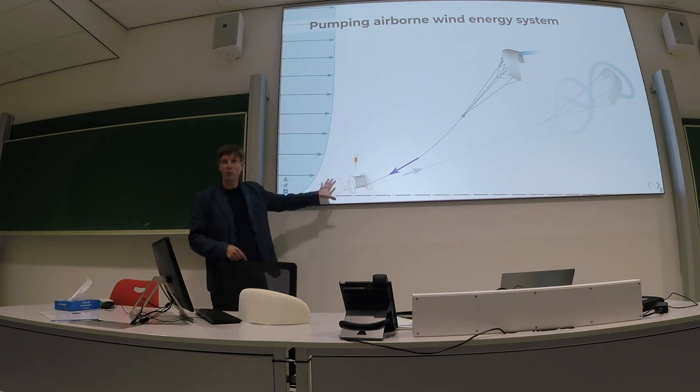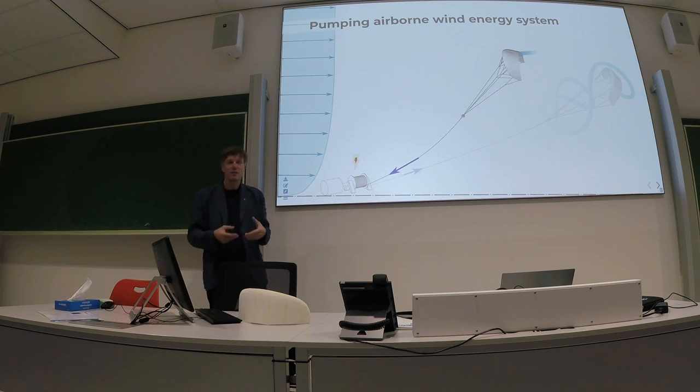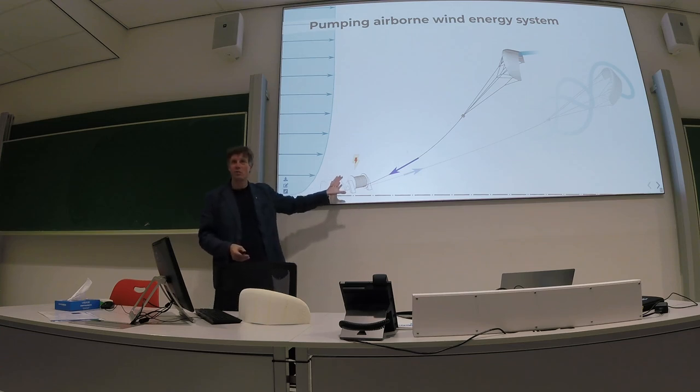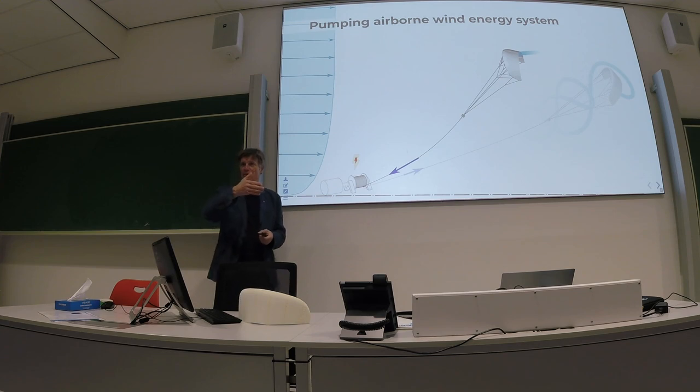If that would be connected to the network, you could also use the network for this, but an electricity network does not like to be fed with energy and taken out in cyclic operation. The grid operator will ask you to have a constant input. So for that reason, we use a battery to store the cycle excess, to only use the cycle excess and keep the small part for the retention.